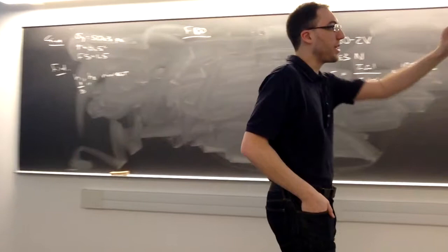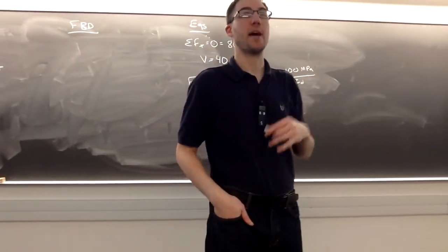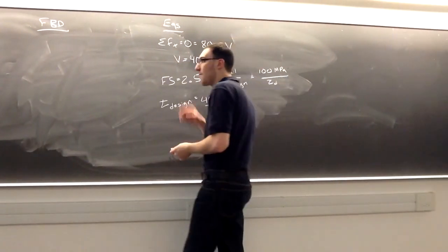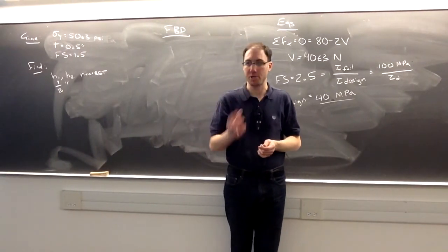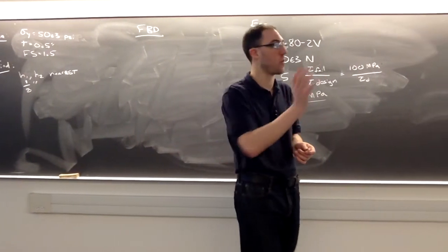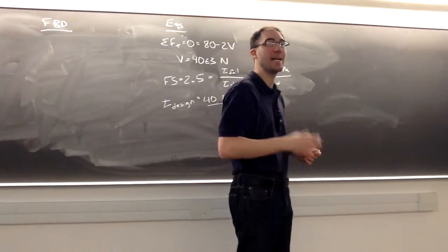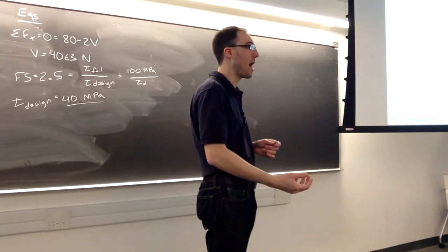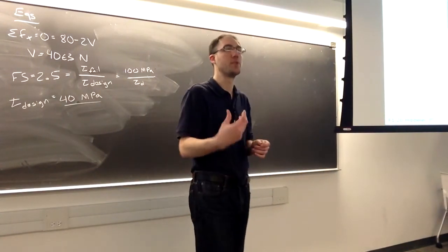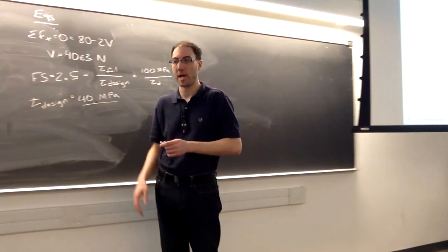Like we discussed, the two sections AB and BC have different internal loads. Every time we have a change in internal load, whether it's moment or shear force or normal force, we need a separate free body diagram. We're going to continue this once we get to chapters 4 and 5. We're going to see the same thing when the torsion changes from one section to another.